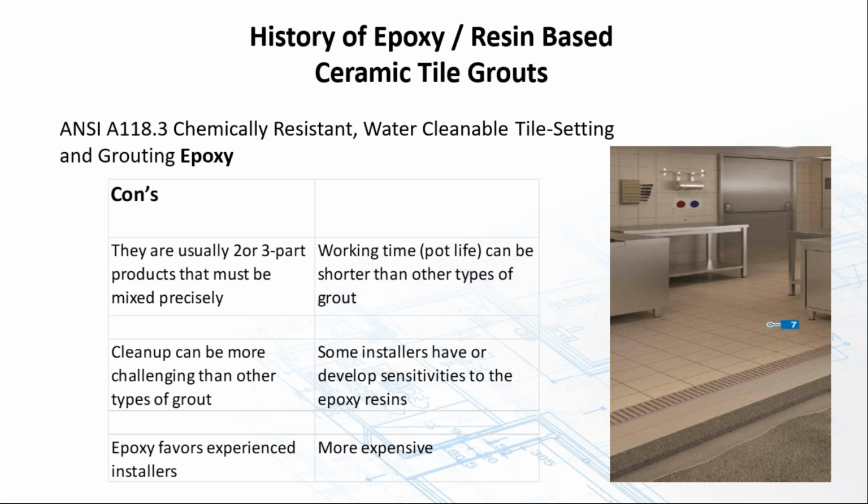With epoxy, you do need an experienced installer in working with it. If this is the first time that the installer is working with an epoxy, he should be doing some mock-ups before he starts it on your floor. And they are definitely more expensive to use, both in the cost of the materials and in labor.